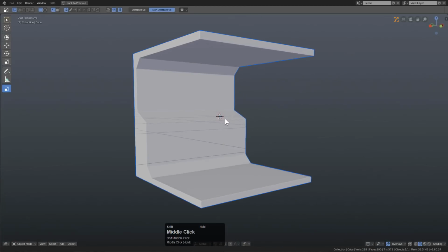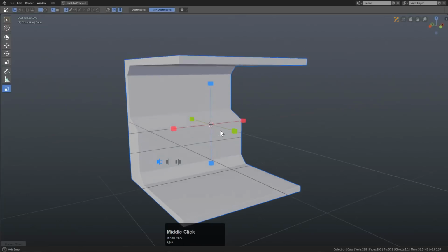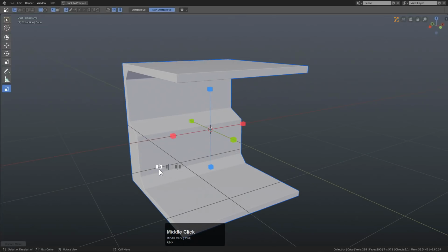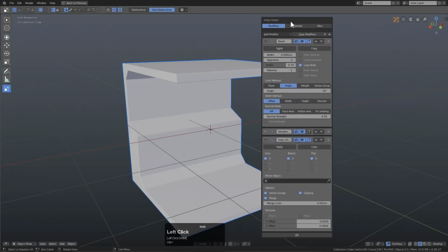Now right here, I want to throw out a PSA and shout out to AR, who pointed out so kindly to me when we were meeting about Boxcutter for about 5 hours yesterday that I've been using the mirror all wrong. And I was the one that actually suggested that we went in and made the modifier use the bisect. But right here, I'm going to mirror it on the X and use Control tilde to look at our helper.